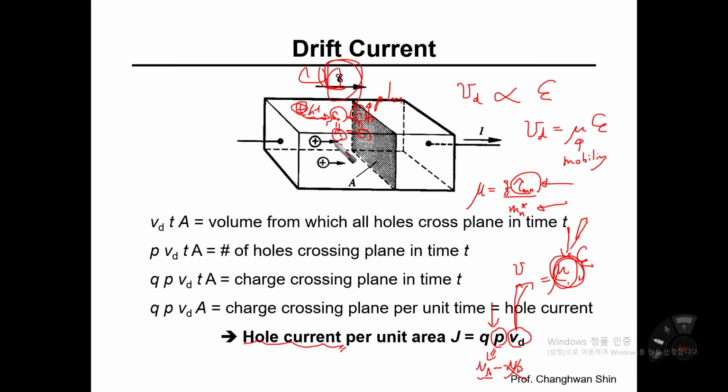And this is p-type silicon material, so at some places boron is replacing the silicon, right? This boron is ionized as being negative, so the holes' traveling direction would be affected by this ionized impurity. So ionized impurity scattering would happen. All these scattering events have been merged into the concept named mobility, right?